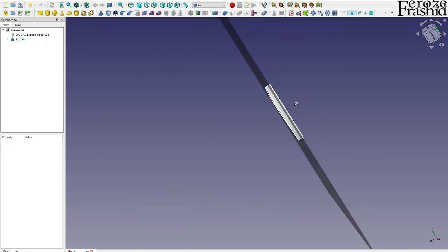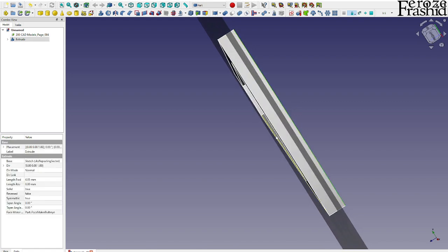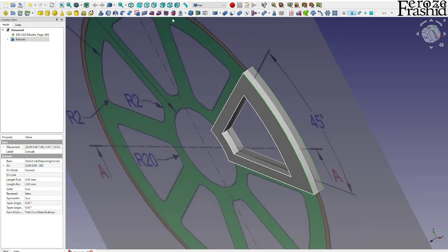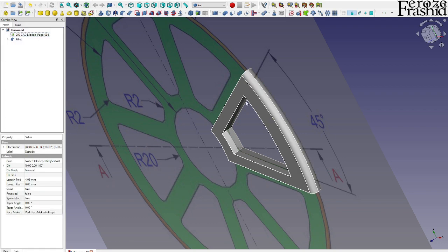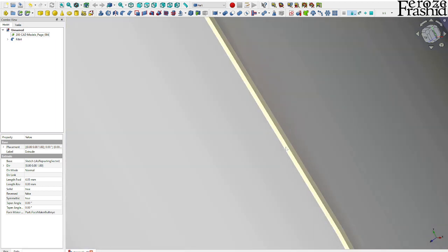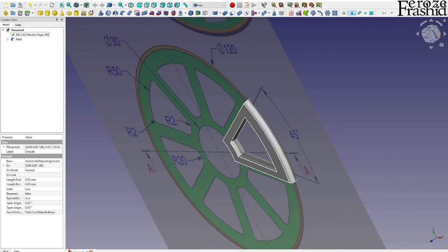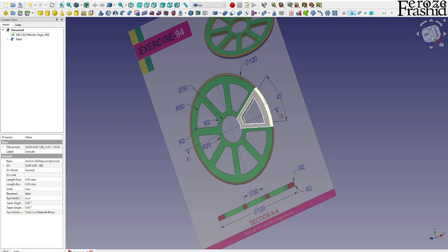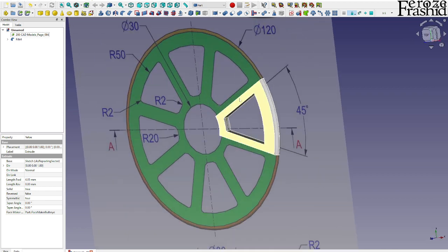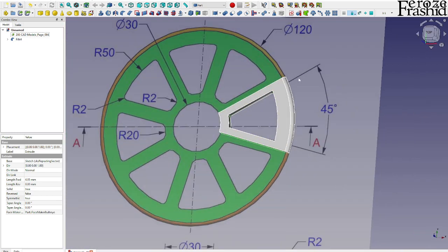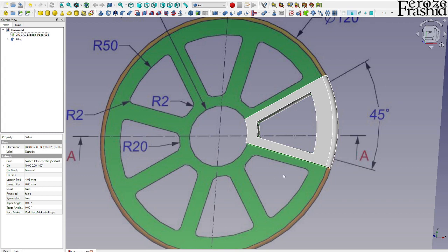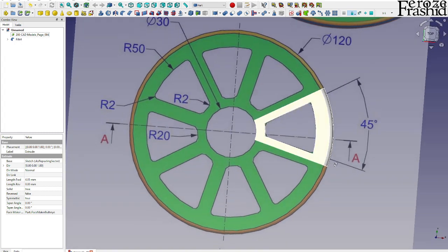All right, now what I want to do is select this line, and obviously this line, and make it a chamfer. So now I can go ahead and make it 2 millimeter. That way they will be pretty close, but if the extrusion was 4 millimeter, I could not do this 2 millimeter chamfer. It would have to be less than 2, so 1.99 maybe. So either way, there are some inaccuracies, but actually not that big of a deal. So we got our repeating section.